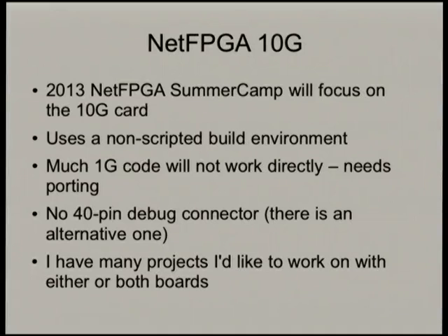Unfortunately, the 10G card is based on a Virtex 5 FPGA, and Xilinx don't support the same build tools, the command line driven build tools. This has been a major stumbling block for the NetFPGA project, and they've had to rely much more on the proprietary GUI based development environment, and they're trying to move a lot of the code that was written for the 1G card across to this new environment for the 10G card.